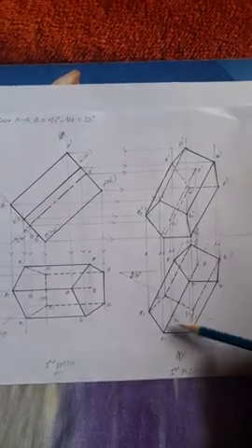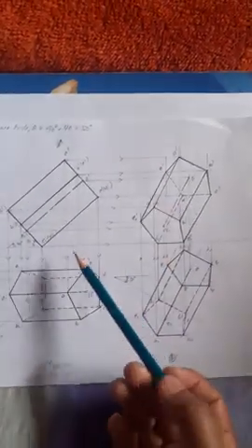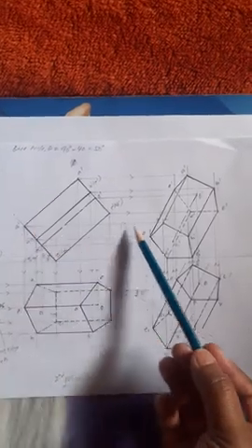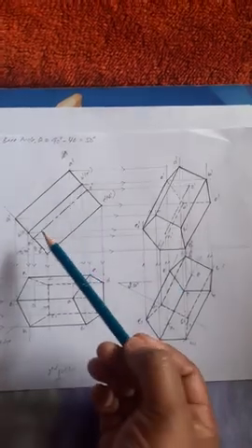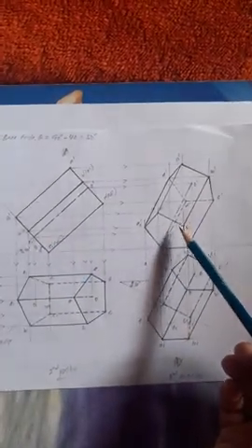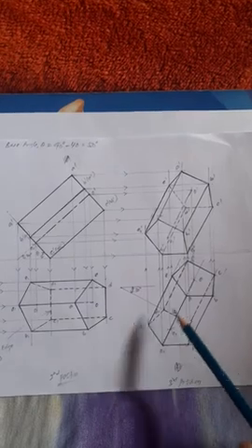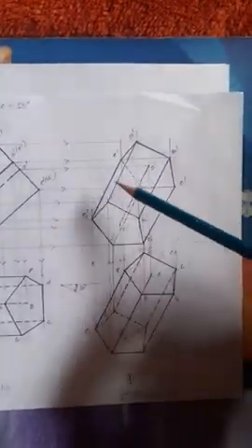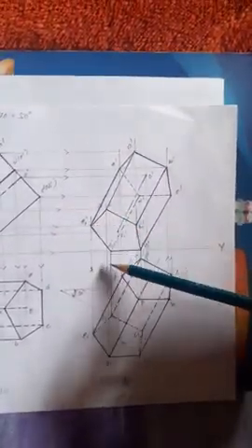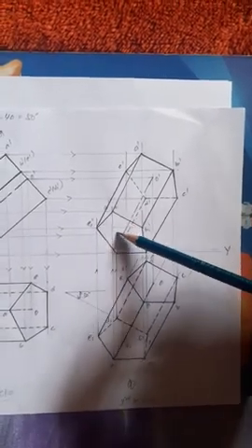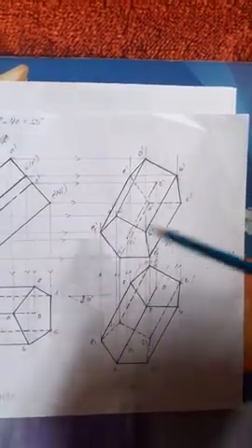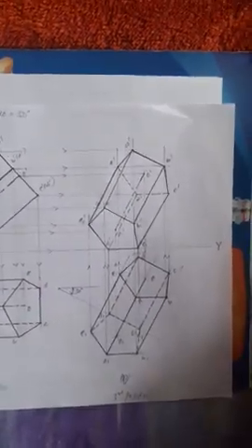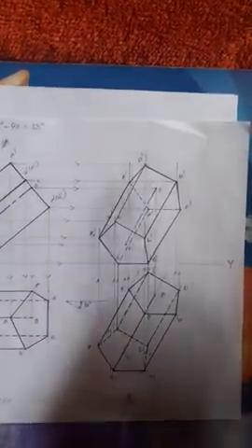So consider the first base. Now A1 vertical projector, A1 dash horizontal projector, the intersection point is A1 dash. Similarly B1 vertical projector, B1 dash horizontal projector. Similarly go for all the corners of the base and also the top face, right? Now once you get the intersection points and the corners of the base and the top in the third position front view, then you apply the rules of visible and invisible lines. How do you apply them?